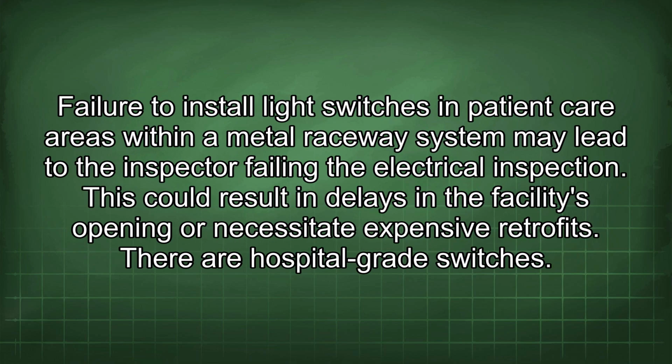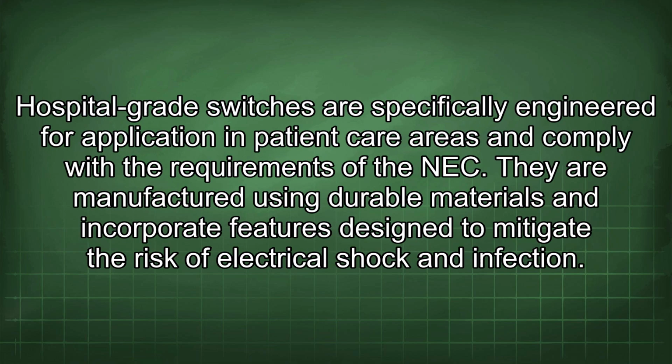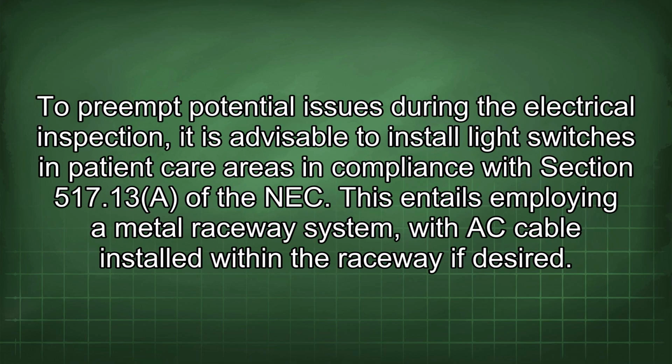Failure to install light switches in patient care areas within a metal raceway system may lead to the inspector failing the electrical inspection. This could result in delays in the facility's opening or necessitate expensive retrofits. There are hospital-grade switches. Hospital-grade switches are specifically engineered for application in patient care areas and comply with the requirements of the NEC. They are manufactured using durable materials and incorporate features designed to mitigate the risk of electrical shock and infection.